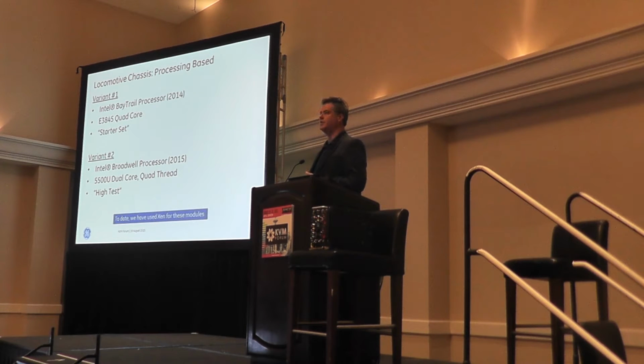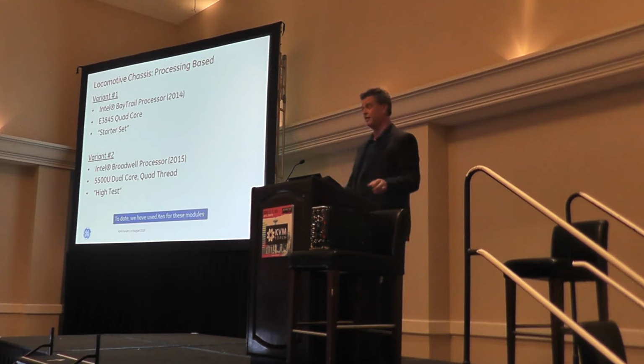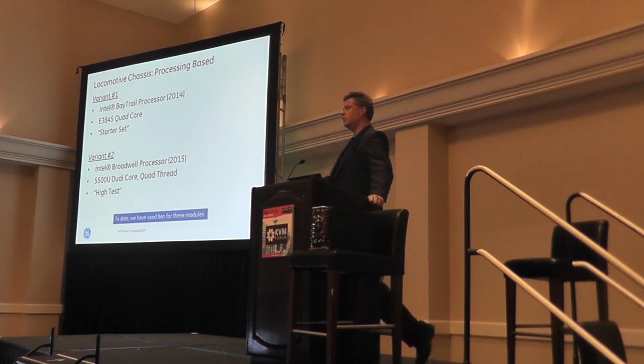So we spend a lot of time getting our heatsink design right, getting our heatsink for the RAM design right, to make sure that our platform can operate at 70 C with no fans. I can tell you that even running that 5500U, Broadwell is pretty difficult to get there. So certainly if we went to a more traditional i7, we'd have no chance of getting there.